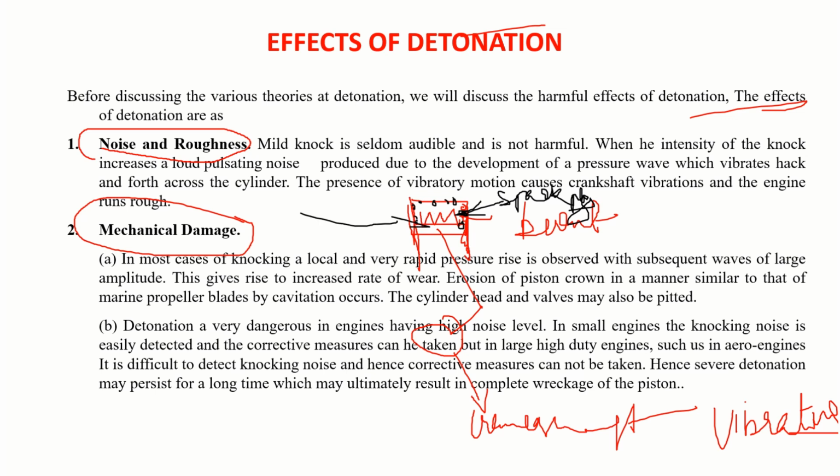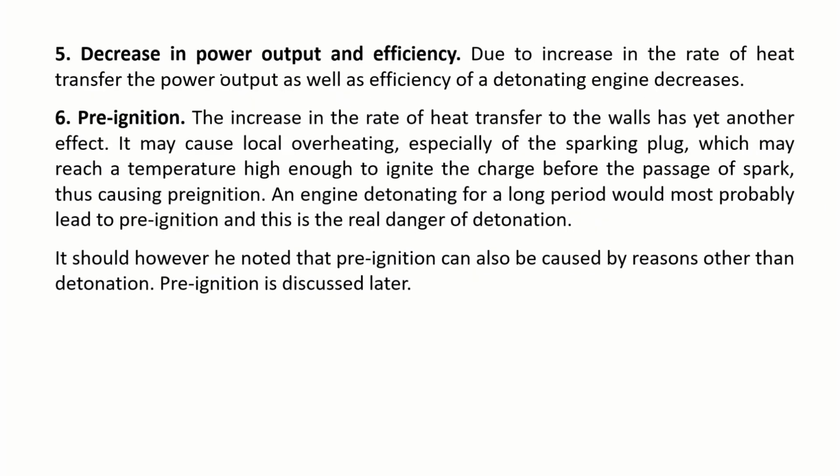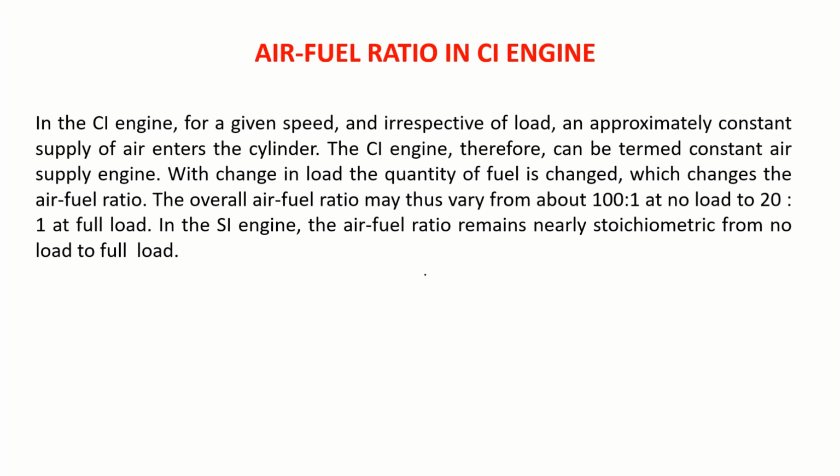And another thing is, the temperature and pressure are so high that uneven expansion of the piston takes place and piston seizure may occur. It leads to complete damage of the engine. So that is what the danger is. That's why we have to carefully design our engine parameters to avoid abnormal combustion. Okay, this is what exactly I was talking about.